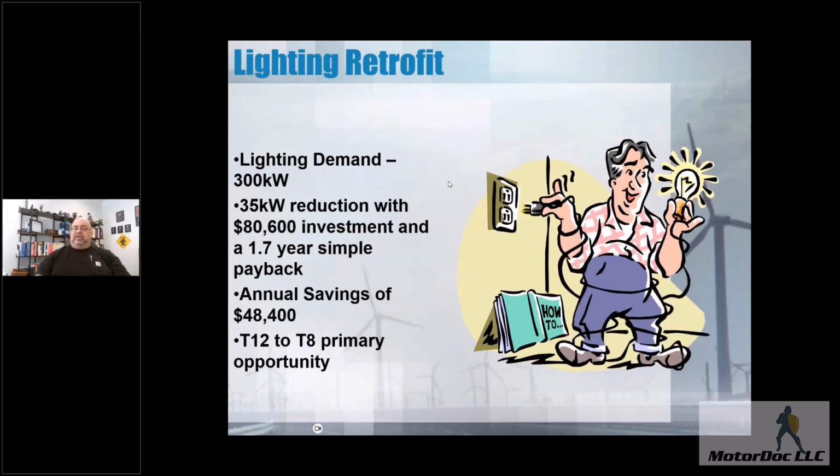Now, lighting retrofits, and this is interesting because in a recent project, we started discovering that LED lights increase your cost due to a significant impact on harmonics in the system. We just did a study at a plant, and we were monitoring for a different project. So when I do an M&V project, I do what's called a Class C, where we look at the actual energy meter from the utility. So we get that utility data, which you can get, especially in the US, in quarter or half hour increments. And then we were able to use that and tie it to things.